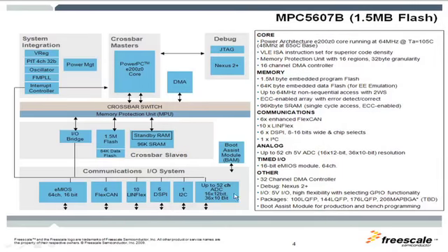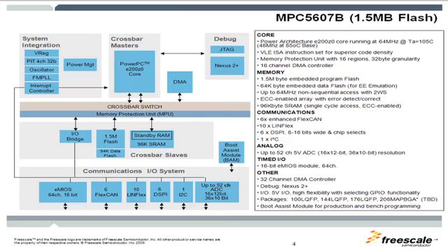Looking at the peripherals on the bottom, the EMIOs, this is the timed I/O. And we'll get into this in a few hours. We have CAN for CAN communication. This works off of a message buffer architecture. So we have mailboxes. You set up a CAN message and you say go, and the hardware will take care of it. You set up for receiving a message from an ID, and you say go, and hardware takes care of that too.